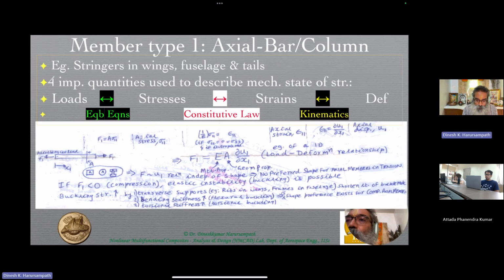So coming back to what we're doing over here, we saw that once we combine those three equations, we ended up with this particular equation that you see over here, namely F1 equal to EA times dou U1 by dou X1, which we can also write more simply as U1 comma 1. And once we have that, as Nafis pointed out, we could integrate for U1 and solve for U1 using the boundary condition, which in that example that I showed on the whiteboard was fixed at this end, and therefore we knew U1 equal to 0